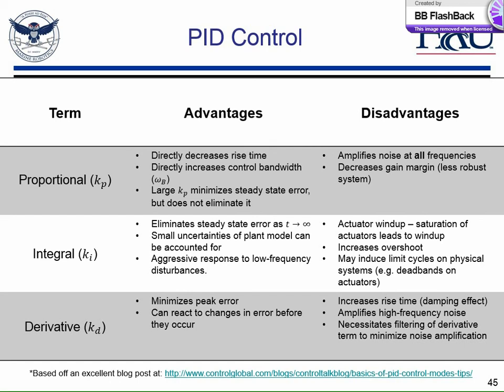But it leads to something called actuator windup, where if you look at our graph again, right? If we have our desired step right here, and this is our system response, the entire area of the error is getting integrated, right? So you have this giant control effort going into here, right? And oftentimes what's going to happen is that you're going to saturate your motor. You're going to saturate your actuators.